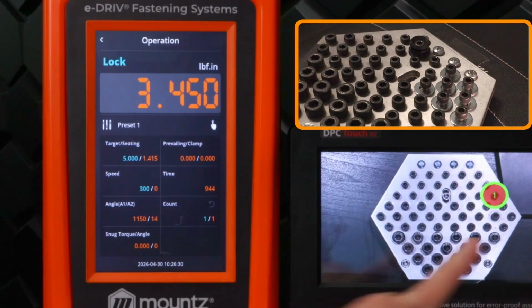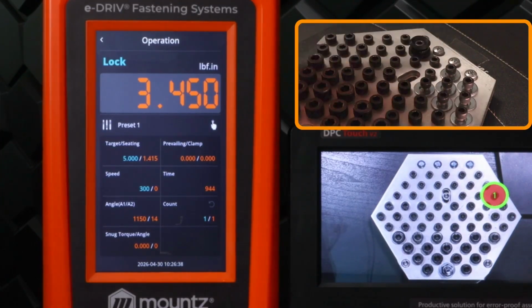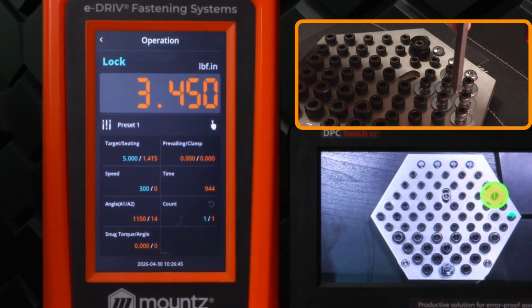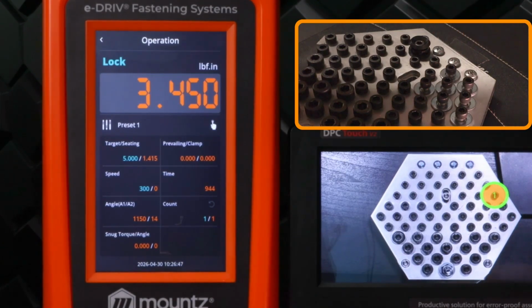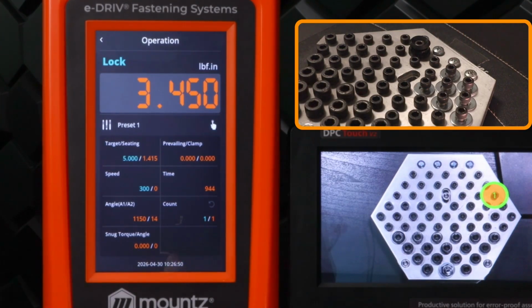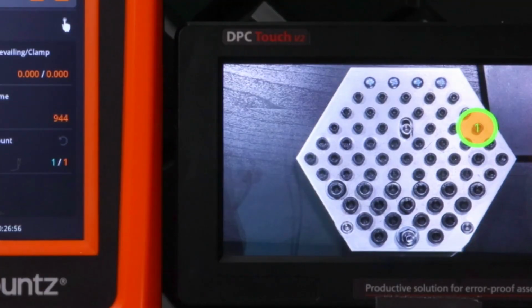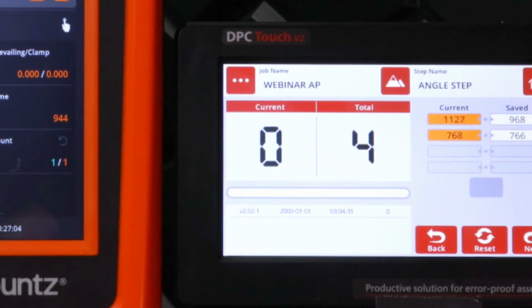Basically, the message on the display is telling us where our fastening location is. If we come to this location, you can see that the tool will now unlock, so we can use it in that location. With the Posi Touch, I haven't quite finished the actual fastening sequence here, so let's go ahead and look at programming that here. It's slightly off just a little bit, but we should be all right.